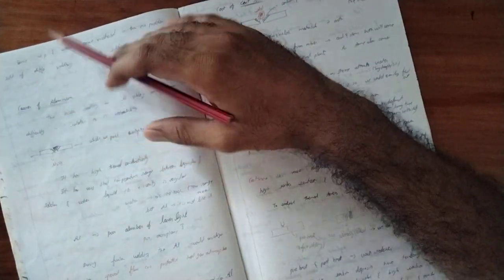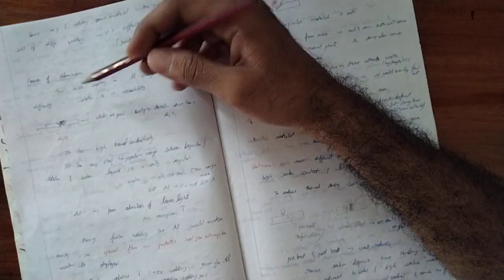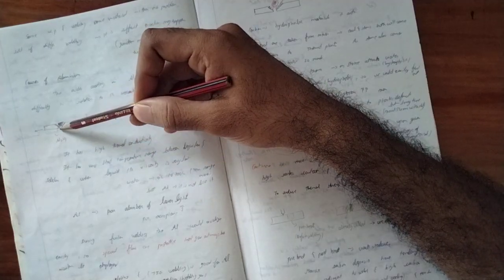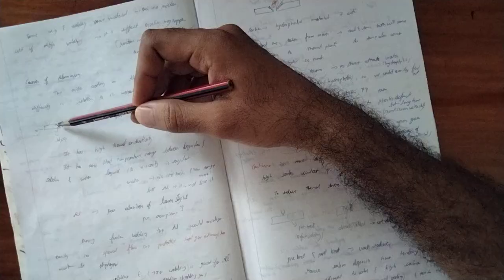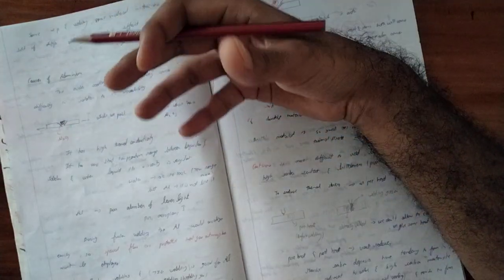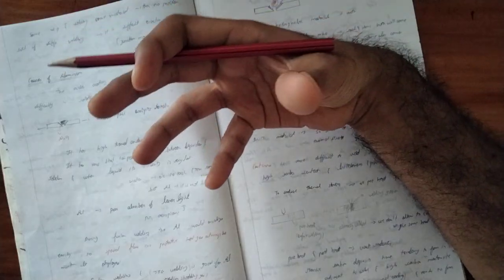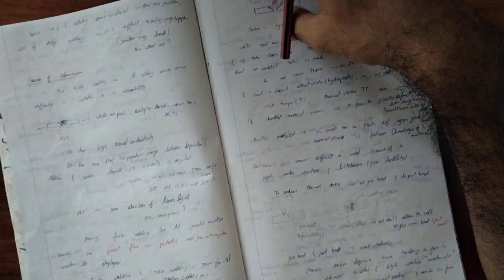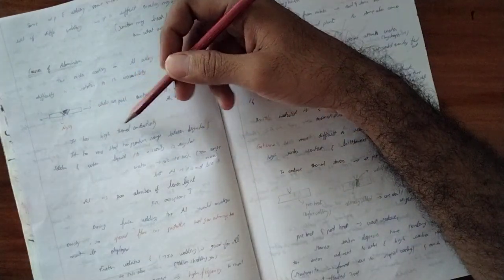So the junction may break. Okay, so next one, you can see causes of aluminum. Why is aluminum so much more difficult? The oxide coating on the aluminum alloy sometimes causes difficulty in weldability. Okay, because you can see the aluminum oxide is present here, and here. Suppose you just weld it, the welding material and the oxide material don't have adhesion, it means cohesion, to easily merge and diffuse. So when we pull, the workpiece breaks, and this is because of Al2O3.